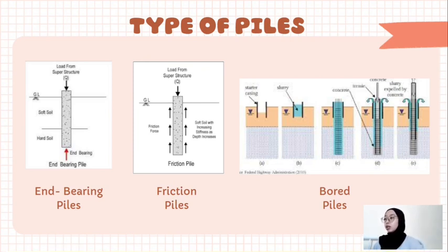The third pile is bored piles. Bored piles need to be augered into the ground to form a hole that workers can later fill with poured concrete. The benefit of this type of pile is that it's cast into position, meaning that bored piles are extremely secure. Construction projects in cities use bored piles because the installation process results in less vibration when compared to other methods.